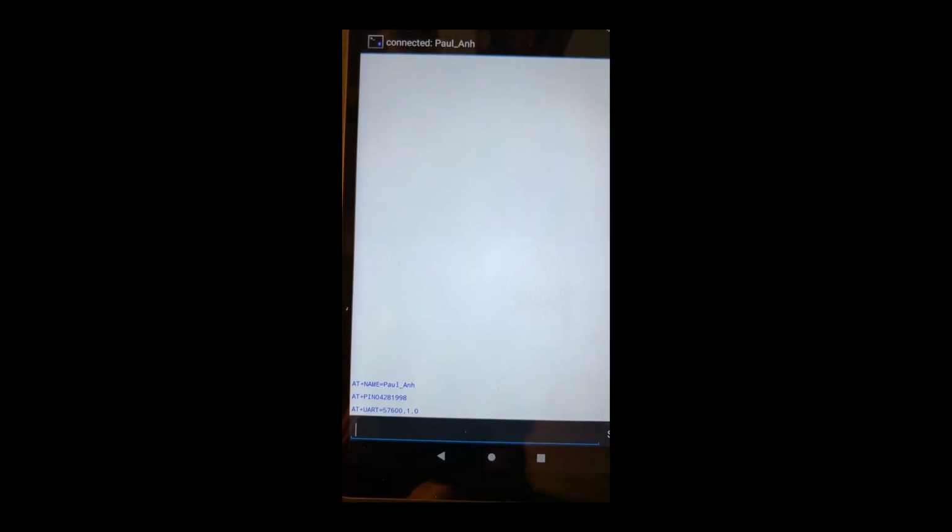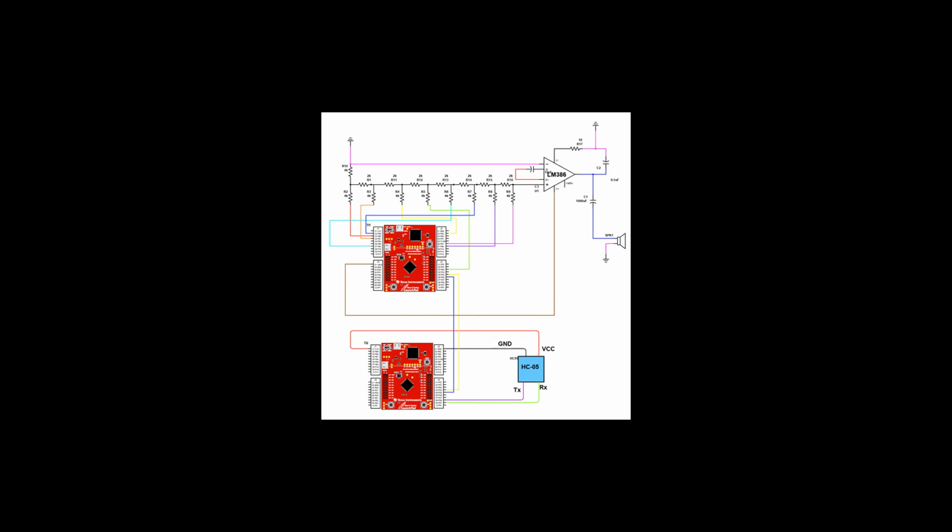In conclusion, this project served well in helping us become familiar with the concept of the UART and ways to communicate through serial interface such as real-term, PuTTY, teraterm, and so on. The input from the smartphone was able to communicate using Bluetooth to the first microcontroller. Then, the second microcontroller grabbed that data through UART communication and sent that data into a DAC which sent output to the speaker. The noise the speaker made depended on the signal that the phone sent.